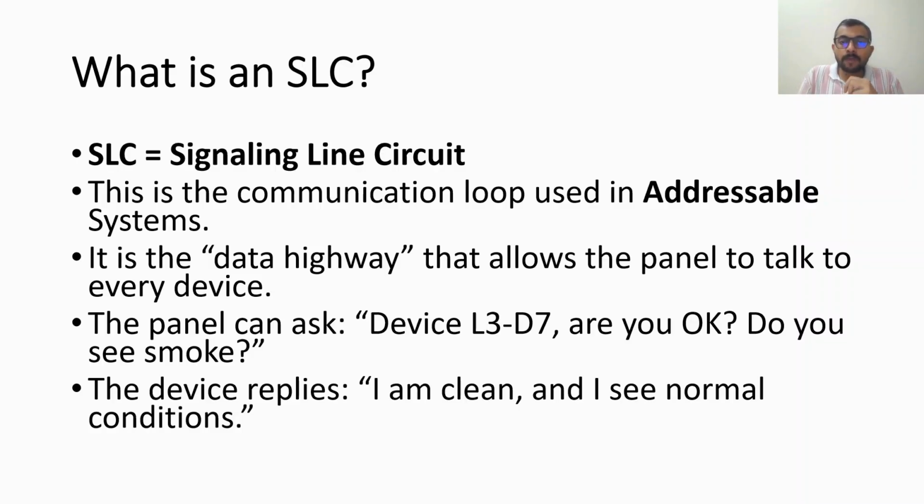The panel will maintain constant communication with the devices, and for each question of the panel, the devices will respond based on the situation. If the situation is normal, that device will tell the panel that there is no abnormality, everything is normal. And if there is an abnormality, say it is a smoke detector, the smoke detector will say, yes, I sense smoke over here.